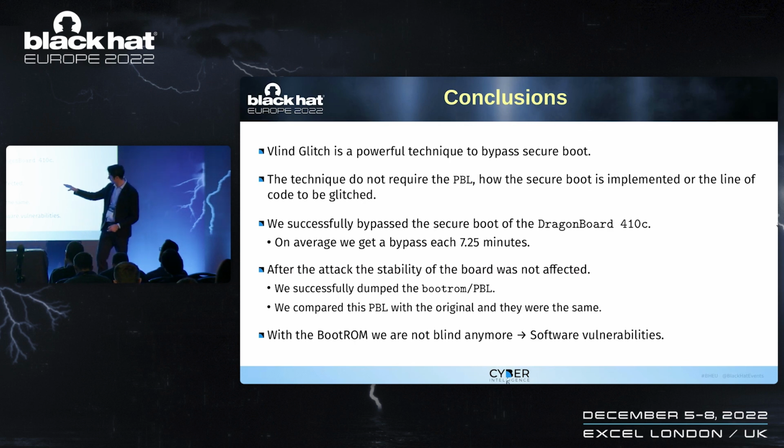The important thing is that we also created a more advanced payload, not just a string: a software PBL able to read and write memory. So we dumped the PBL, the bootroms. This is a mechanism to dump bootroms, so you can use this approach if you want to get bootroms. We compared the PBL with the previous one from when secure boot was not enabled, and they were exactly the same. This proves that the attack is not only successful, but the board is stable enough to operate normally. With the bootrom, we are not blind anymore, which was one of the goals.